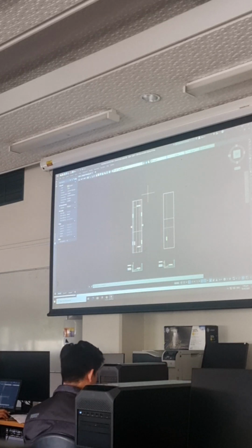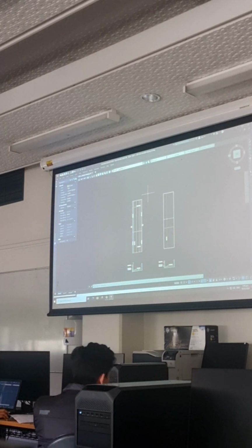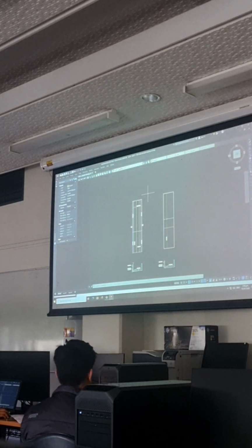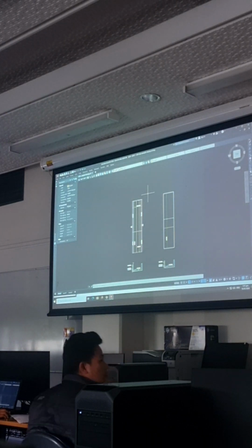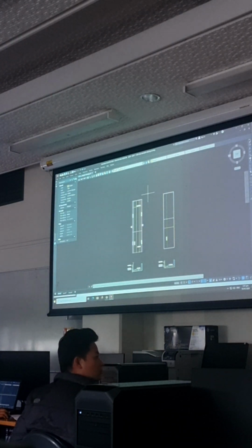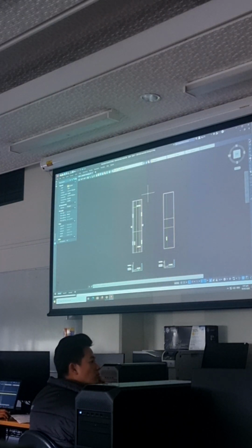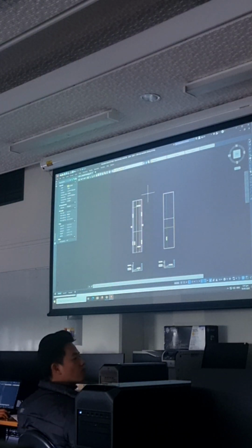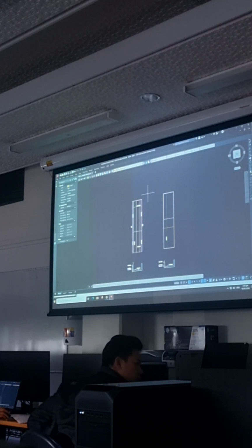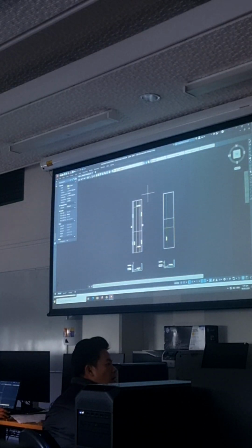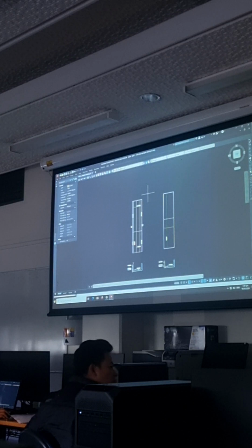Just out of interest and just to pull apart this design. Normally, when we do things like channels like this for water racing, or we do retaining walls or anything that goes on and on and on, we normally stick out a whole bunch of bars ready to be joined onto for the next section. And this one doesn't, so this would be a complete section that will join on to the other end with another one that looks similar to this.